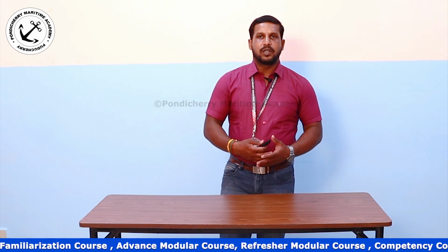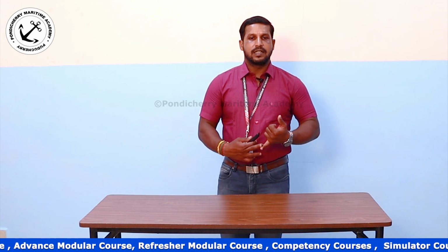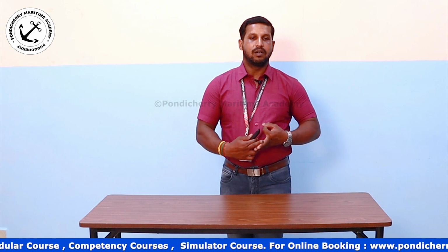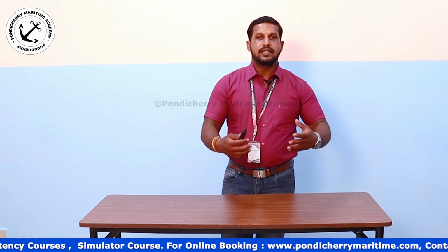Whatever equipment you use, either a toxic gas detector, multi-gas detector, oxygen meter, explosimeter or tank scope, these equipments have to be calibrated before we use. Before every use, these equipments have to be calibrated by means of span gas, right? Before using the equipment, you have to be familiar with the operational criteria and the limitations of the equipment.